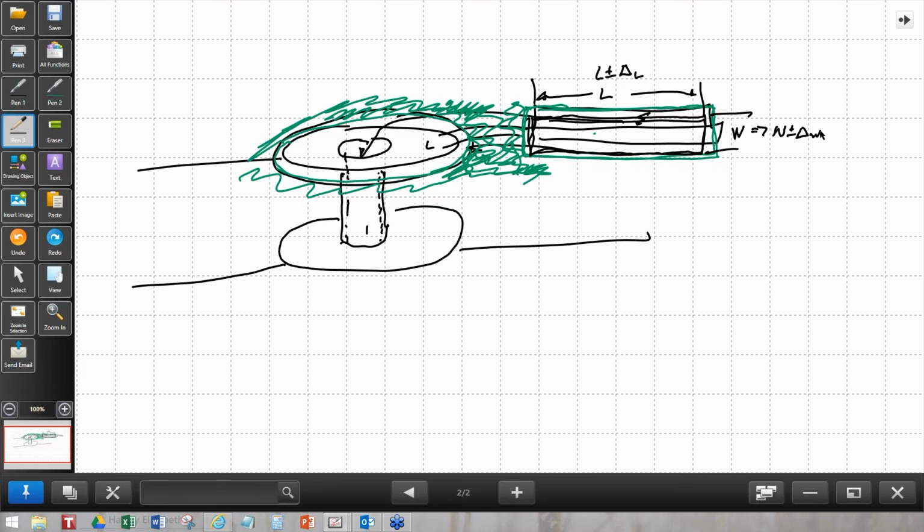The solder mask itself will have a hole that's slightly different than the size that you said, and it also may be misregistered slightly based on manufacturing tolerances. So you want to make sure that this opening in the solder mask is far enough out that even with all of those things going on, you're not going to get a problem.